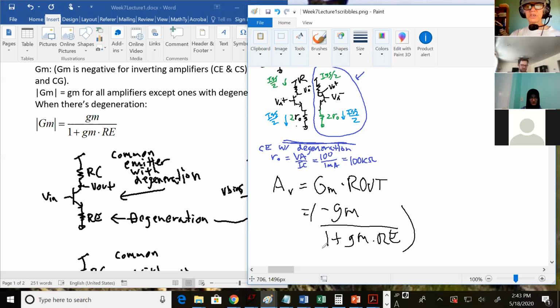So that's your big GM. And then your R out. What's your R out for that? RO in parallel with RC.